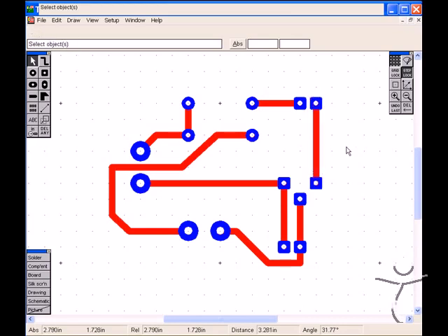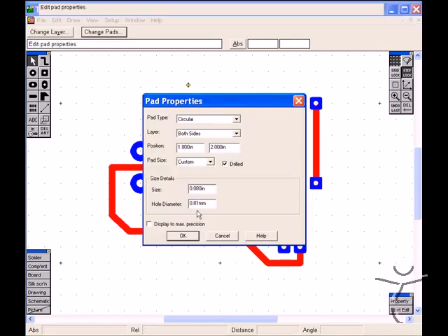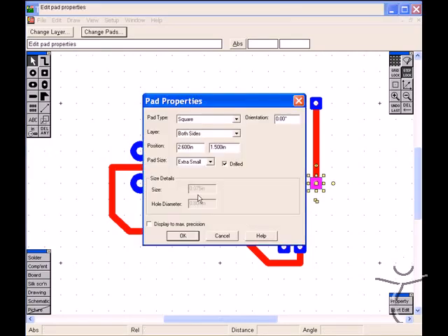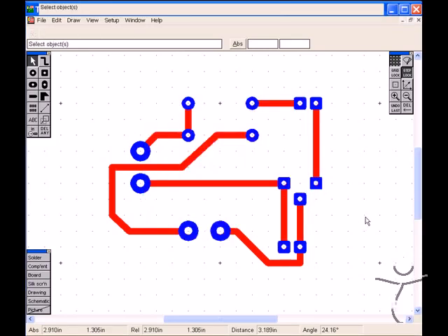So now it's a matter of going and doing the engraving, but it's also worthwhile checking the size of the holes. So if we go here and check the property, it's a 0.81 millimeters. This hole here is a 0.8. So if we're not careful, we'll do our selection of our drills, we'll get the 0.81, but we won't get the 0.8.